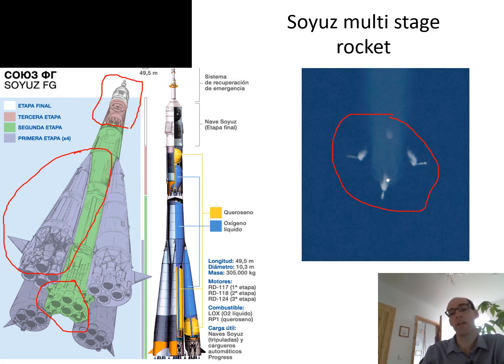So a staged rocket is designed to basically make the best out of a bad situation. In principle, an infinite number of stages would be best. Some means of basically dropping each stage individually, but that doesn't take into account the fact that the engines themselves and the fuel systems have mass, so you know that wouldn't work out. So most rockets usually have 2 or 3 stages. 3 is very, very common, and Soyuz is no exception. The different stages will often use different rocket engines and will often have different fuels, but that again is a little bit more complex than I'd like to get into today.